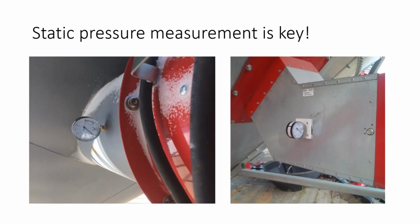Now, with all these different systems, the real key is measuring your static pressure. For some of them, namely the simple aeration tube, the T-rocket, and the cube, you can literally put your static pressure gauge on and start up your bin empty, and see what your pressure loss is. I like to be at 1 inch or less, basically injecting directly without any grain.